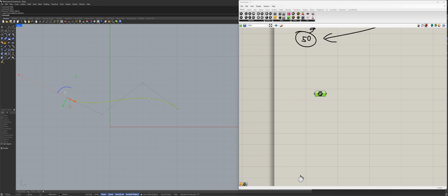Now this bridge is live. And actually, let me prove that this is the bridge. If I click on the panel and figure out what's inside, it says referenced planar curve, and it references the original one. If I select the original one and hit delete, that's it. It's broken now. There's nothing there because the reference curve is no more. So this curve is here. I can just hide it to visualize it from the Rhino, but as you can see, it's still there. It knows where to look, right?